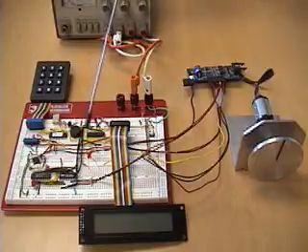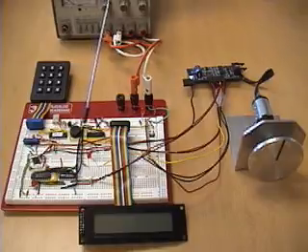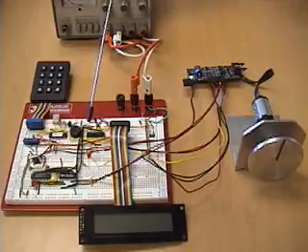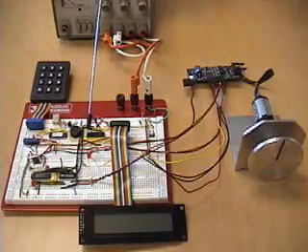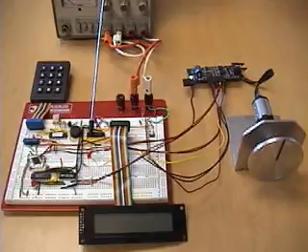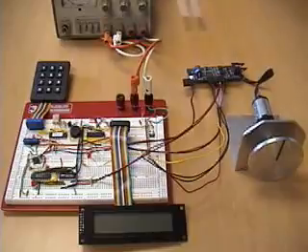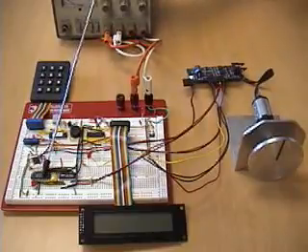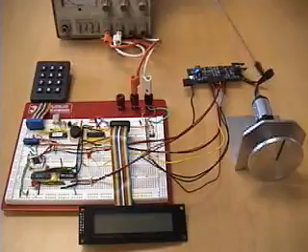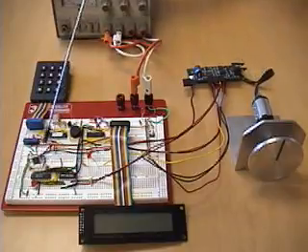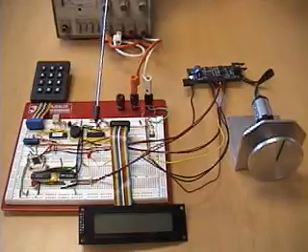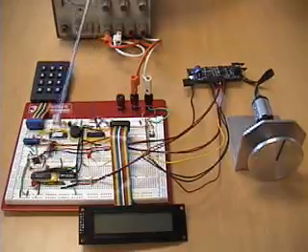Now, let's talk about why we have two microcontrollers here. The main reason is we have a limited number of output ports on one microcontroller. Therefore, we decided to use two, one of which is the master controller, or the main controller, that controls the DC motor. The second microcontroller, the F84, provides input data from the encoder and then transmits that data to the main microcontroller using a serial interface between the two.